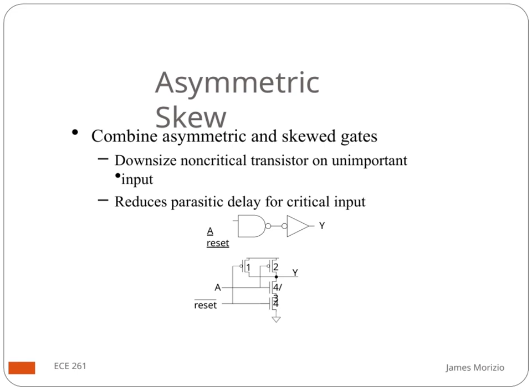You'll notice that the transistor sizing numbers like 4, 2, and 1 indicate how we scale the transistor widths, assigning larger sizes to critical paths and smaller ones to non-critical signals. This selective sizing achieves better speed without unnecessary power or area costs. The reset and output labels here illustrate how this approach is applied in practical circuit designs, balancing timing needs with efficient transistor use.